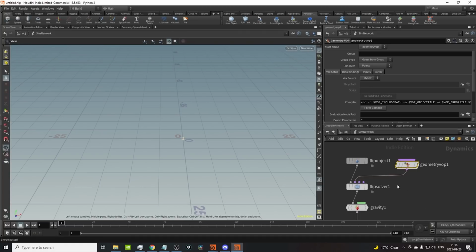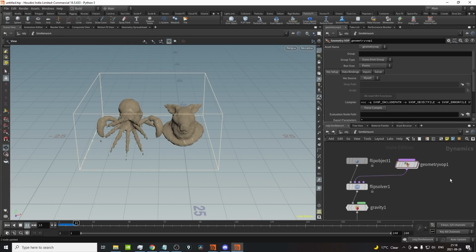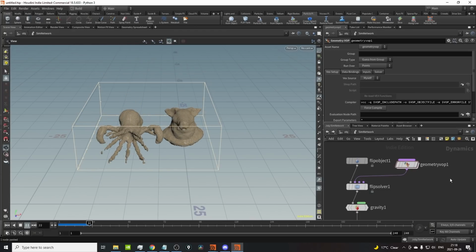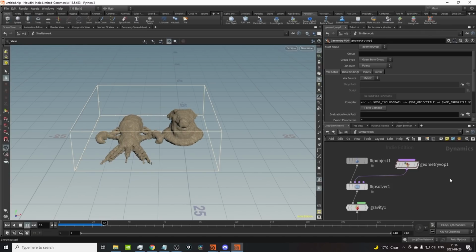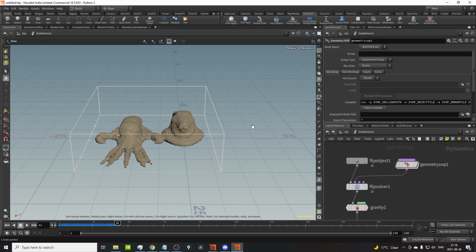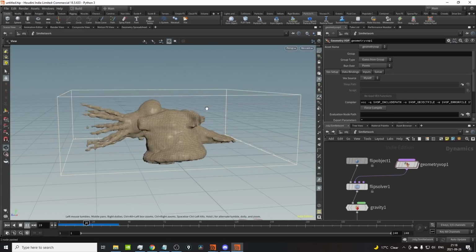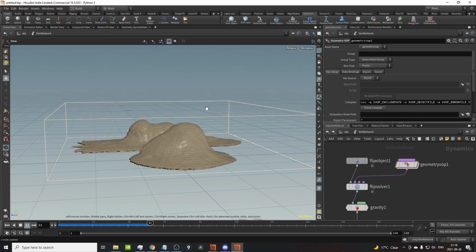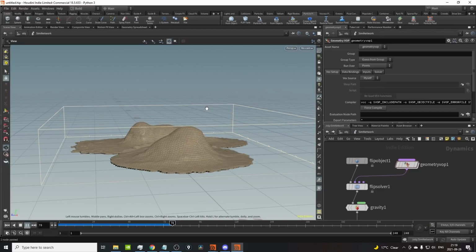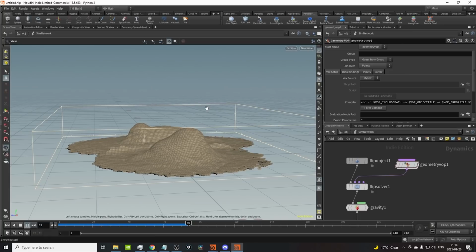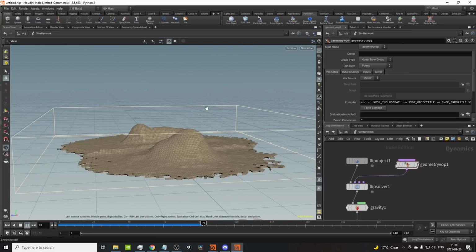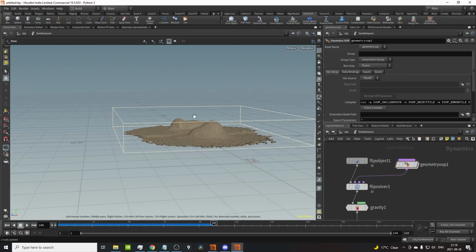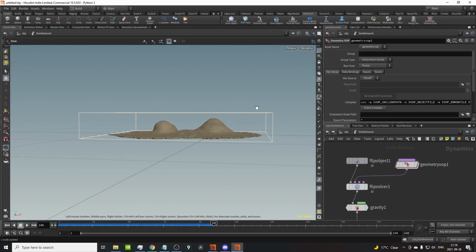So I have a recursive loop automatically, because we're in a simulation, that now slowly scales down our viscosity on the edges. And if we look at this, now we will see that stuff like the tentacles are a lot more floppy, his ears melt, right? It's becoming sad. He's slowly melting in the sun. But everything inside is still staying quite strong with the viscosity, so we're keeping that core, right? And this is an easy way of melting objects using very simple recursive operations and using variable viscosity.